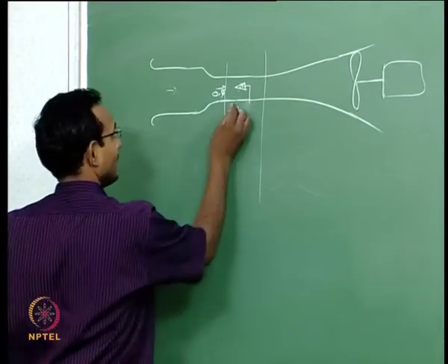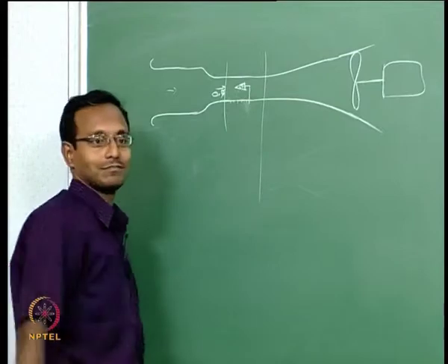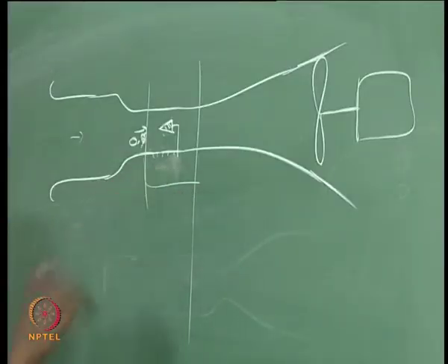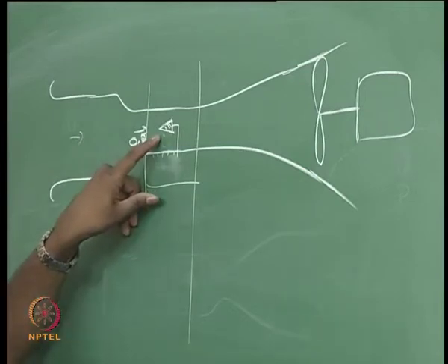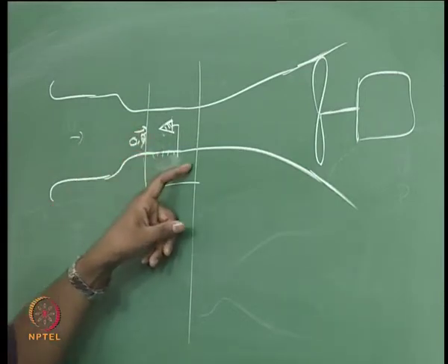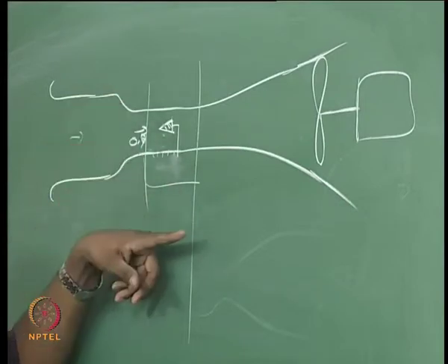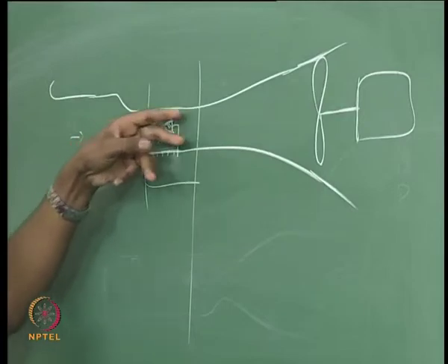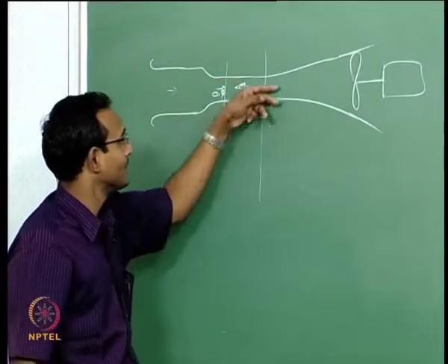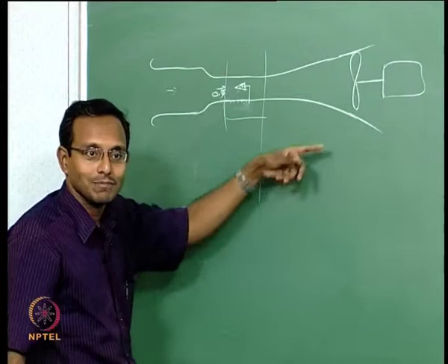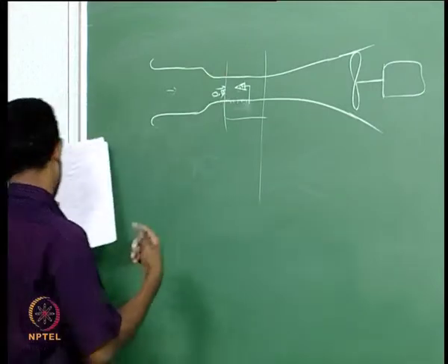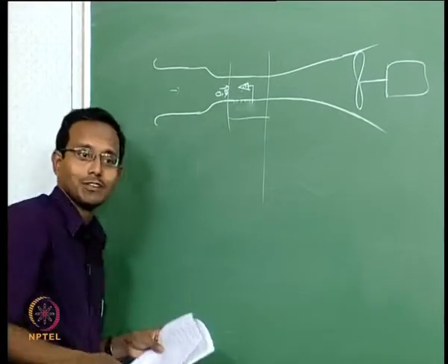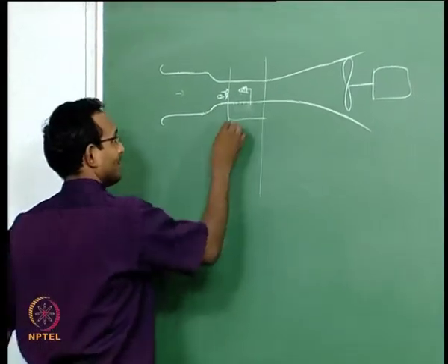What they do is they will put holes on the side and keep this region at slightly lower pressure than what is in the test section, so that I will bleed out some mass flow. If I bleed out some mass flow, now I can make sure that the incoming flow is 0.9, because not all the flow has to go through this, because that is having a choking condition, but this is not. I want to send out some mass flow. Now I have to think about all these extra situations. This is to take care of geometric choking. Next thing is shock reflection.